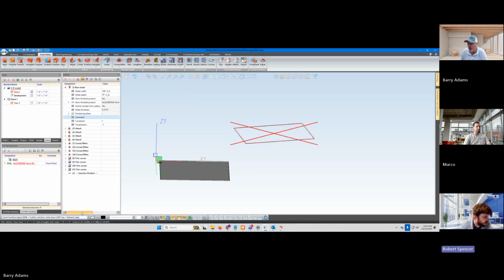Now you have your variable list. Where is it? It's up there with your views, HCM, graphics, properties, variable. I'm looking in the wrong place. Yeah, you know how your views, where your sheets and views are? Right here. So down at the bottom, you got a bunch of tabs below that. Oh, yeah. And you're going to have one that says variables. Okay. And you see how you now see those variables that you just created. Yeah.